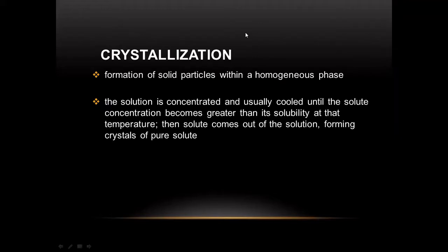So its concentration becomes greater than its solubility at that particular temperature, and as such, it comes out, or in other terms, it precipitates out of the solution, forming what we call the crystals of pure solute. So the process done in order for your solids to precipitate out of their solution is cooling.